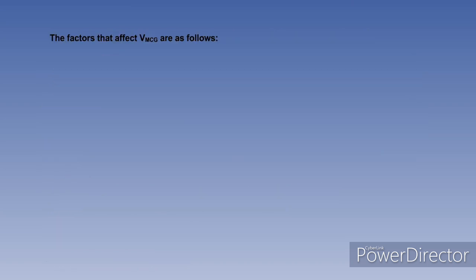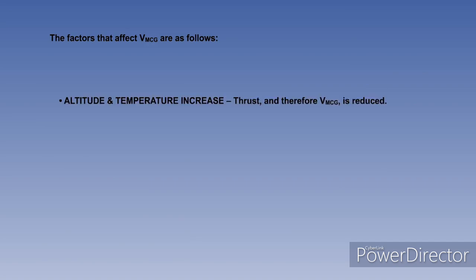There are several factors that affect VMCG. They are as follows. As with VMCA, increases in altitude and temperature will reduce the thrust produced by the live engine or engines if unsupercharged, and VMCG will be reduced accordingly.